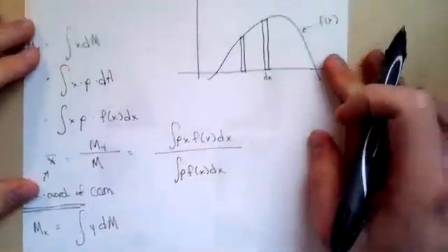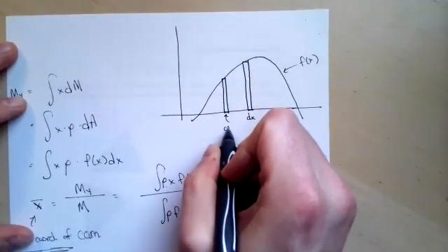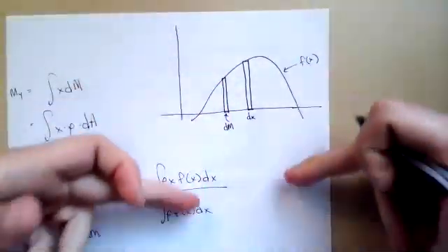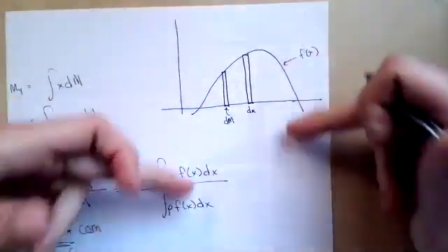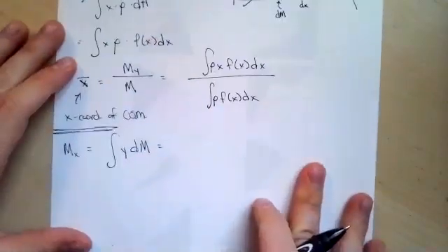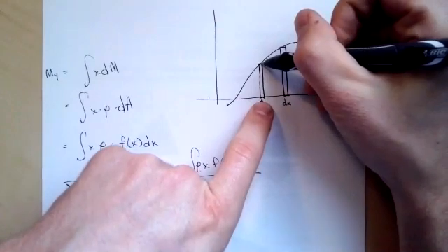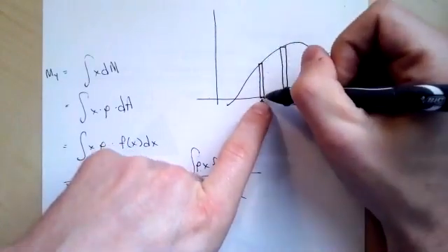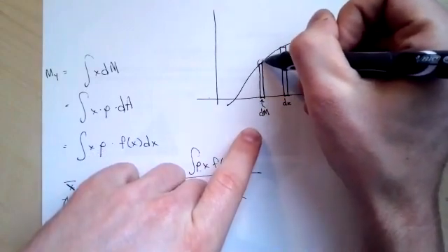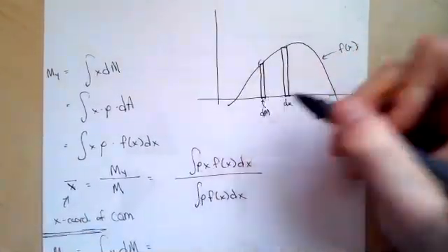So what's going to go on with this guy? Well, each of these pieces is our dm. But now we are rotating about the x-axis, right? So instead, the trick we use is that if we are rotating this bar about the x-axis, the weight of the bar at the end is going to contribute a lot more to that moment of inertia than down here.